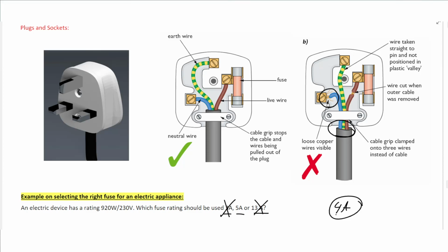So a trick question may come that a person, instead of using a 3 ampere fuse, used a 30 ampere fuse. What happens when you connect this fuse and switch on the circuit? Nothing happens. The circuit works normally. What is the danger? That if the current gets too high, the device will be damaged. So you choose the fuse which is just above the required value.